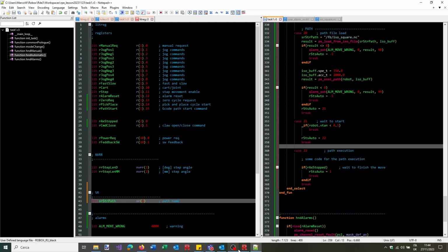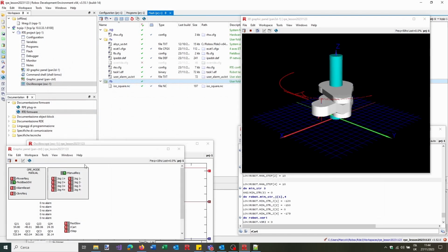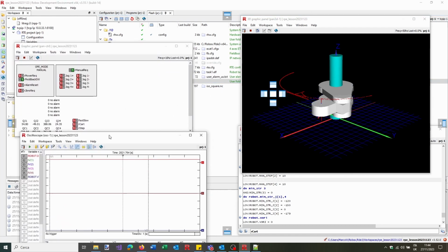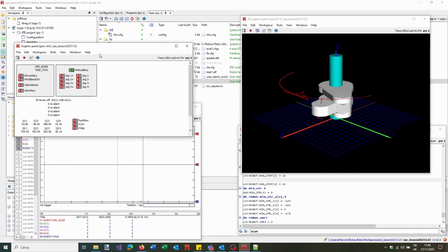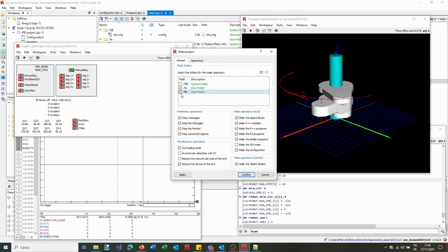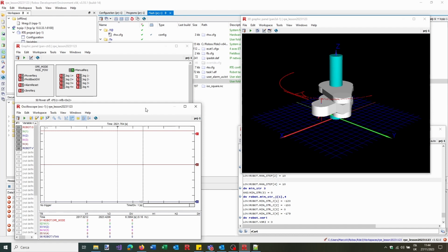Let's save, and now let's make, and we play with these new features. Now, in order to play, I need to take out the power, now make, and while we make, I also select FB because I need to create the FB and load it inside the path. Now confirm, and let's see if compilation finishes successfully.